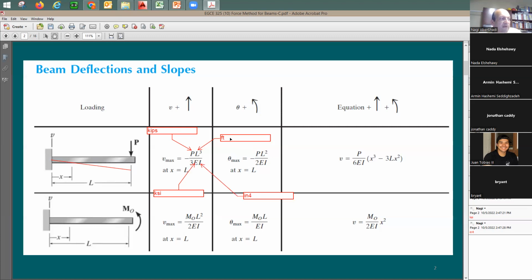I see that I have one foot to convert, and inches twice. It's much easier if I convert this foot into inches before I start my work, and then this deflection will also be in inches, so everything will be in inches. But if you want to do it in feet, that's okay. You'll just spend more time and effort, because you need to convert the inches to the fourth, convert the ksi, and then plug it in this equation. It's much easier to convert this feet into inches, only one step versus two steps.